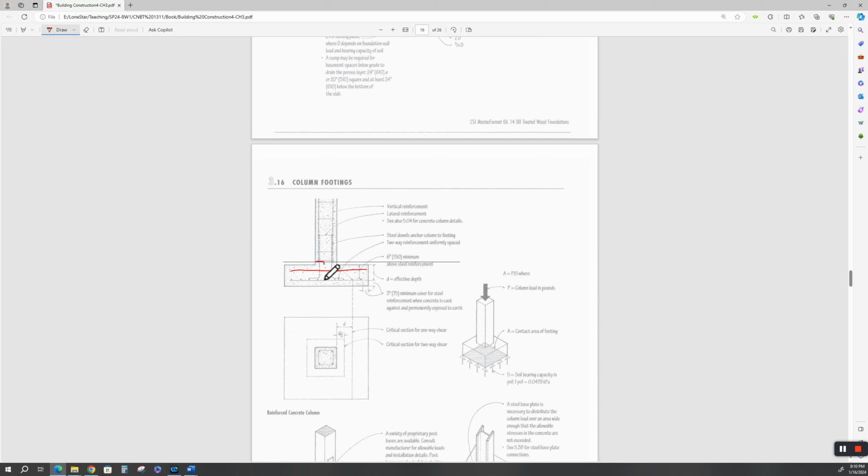They didn't do the keyway in here. All right. Then you'll form your column up, whether it's a square or round column. He likes square columns. All right. They may just drop a sonotube in here, which is a round column form. Your vertical reinforcement, and then this is your lateral reinforcement, are your ties.